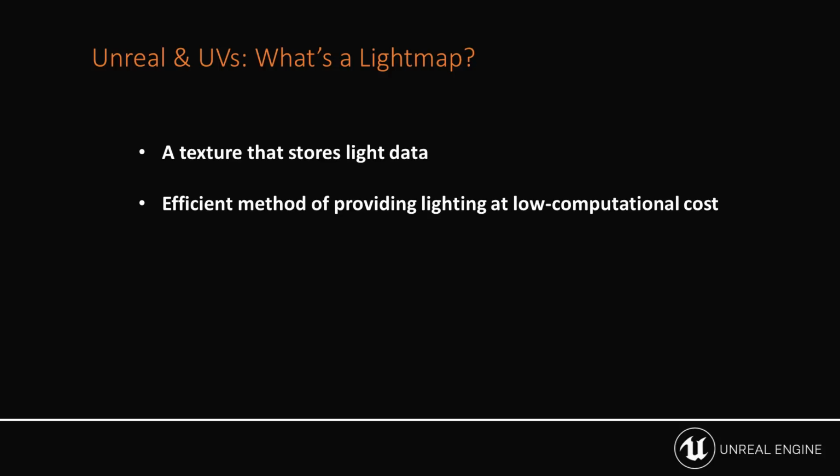So another way to look at this is rather than have a scene full of actual lights, dynamic lighting where it's working in real time and dynamic shadowing that's actually happening in real time from an object, we're able to light a scene, take all of that lighting data, bake it into images, and essentially do kind of a multiplication or an overlay process that'll allow us to have a scene without the cost of lights, but we're getting that same quality of lighting that we expect when we bake it or calculate it out.